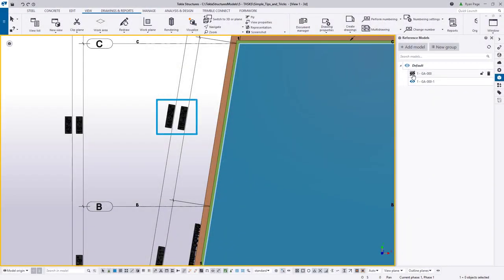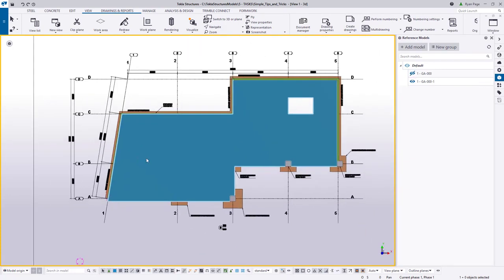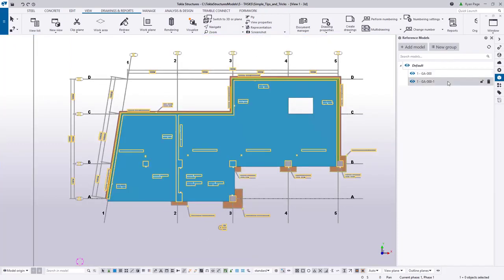If working with 2D references is part of your workflow, then you've no doubt noticed that most PDFs and even some 2D CAD files have masking around the text that makes it difficult or impossible to read. Before going through the trouble of adjusting your representation filters or sacrificing your reference rendering for the sake of a 2D document, make sure to check out the reference model pane.